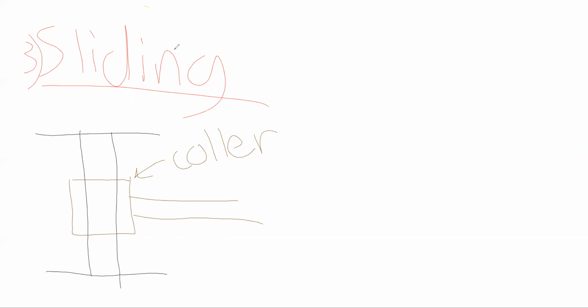So you could probably guess how many degrees of freedom this has. This has 2 degrees of freedom. So this collar basically prevents motion in this direction. So you could say there's a reaction force. The direction, I'm not worrying about the direction right now. I'm just trying to get the correct orientation. There's a reaction force here. This is our XY coordinate system. We have a reaction force in the X direction, right?